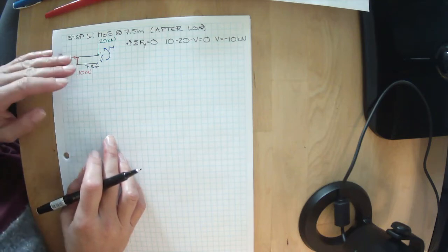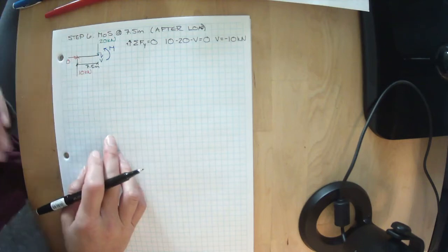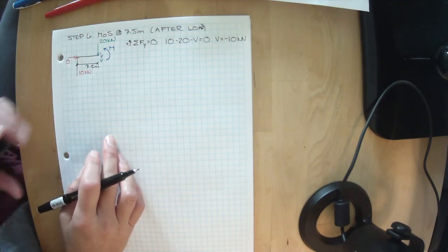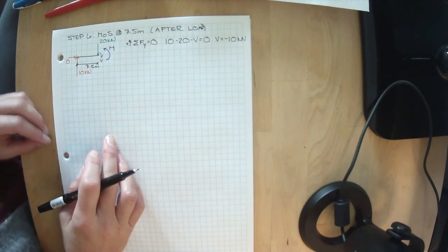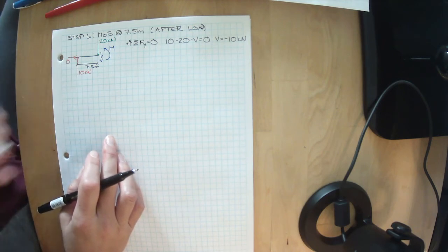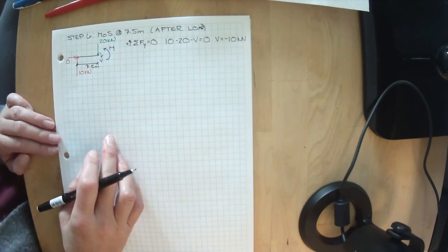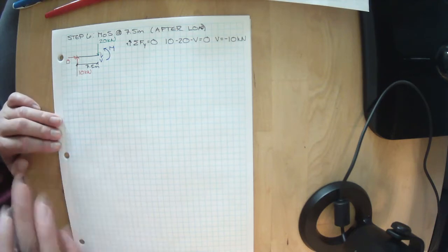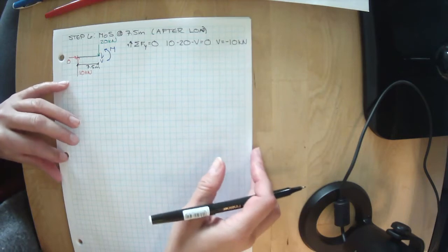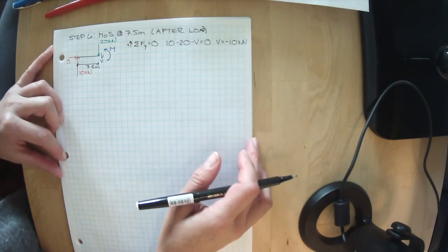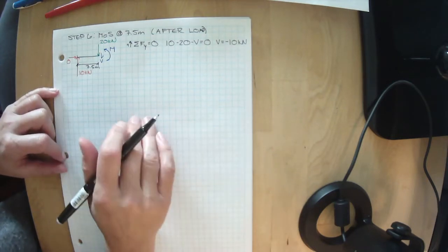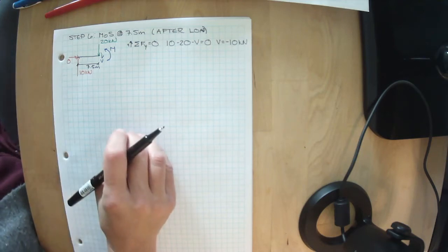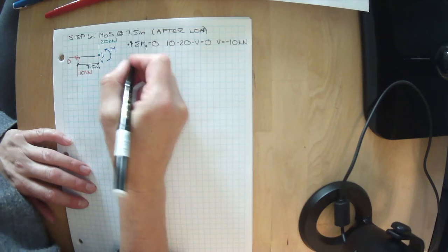What we care about is where it switches from positive to negative. So the absolute value of shear is what we care about as a result. And I'll show you what that means in a minute when we graphically illustrate what these values are. And that's where these graphs, remember last week we looked at axial force diagrams. These graphs are going to come in really handy when we talk about shear and moment diagrams.